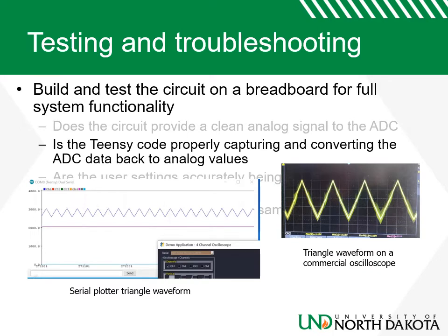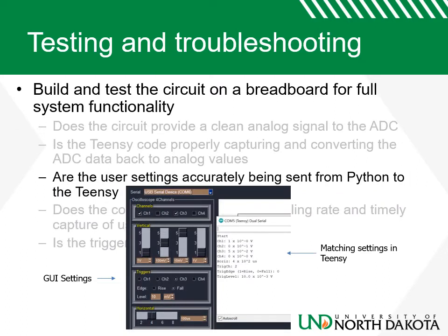For testing the proper capture and convert of ADC data back to analog values, I used a couple of function generators that I have and tested their values and waveforms against a commercial oscilloscope that I also have, and had good agreement of data. I wrote a small test program to make sure the GUI settings were coming in properly on the Teensy. Here are the results of that, showing the agreement of data between the two softwares.